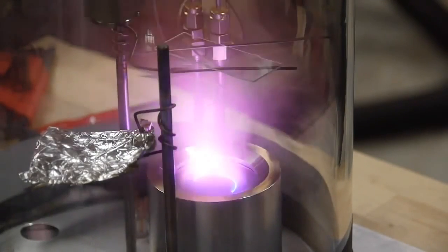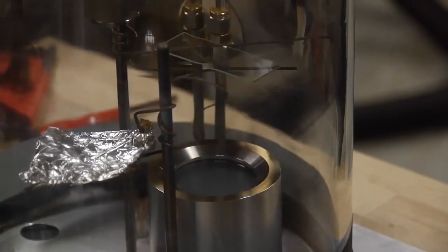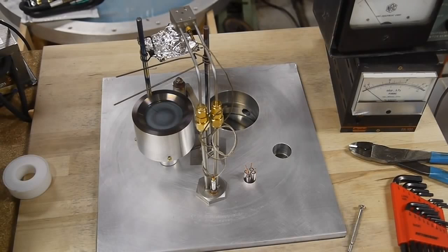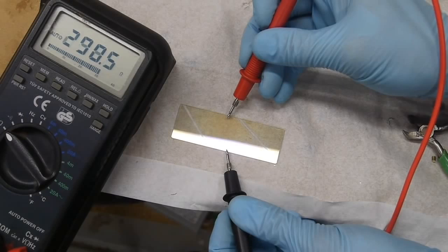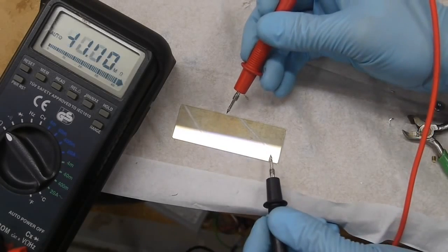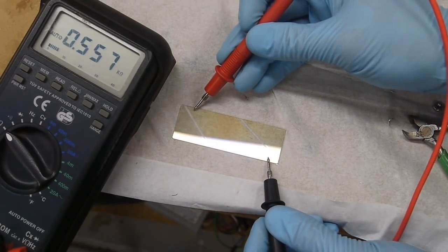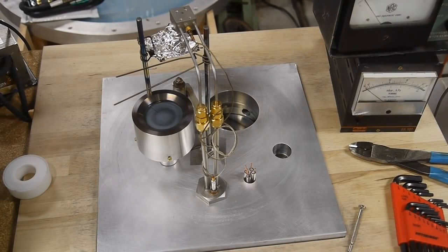Sputtering involves the removal of particles from the source through bombardment of high-energy particles, usually from a plasma or an ion source. Shown is an example of magnetron sputtering, in which a closed magnetic field traps electrons to generate the plasma used for sputtering. One advantage of this method is that it allows for plasma formation at lower temperatures, reducing the presence of background gas which would cause inconsistencies in film thickness and uniformity.